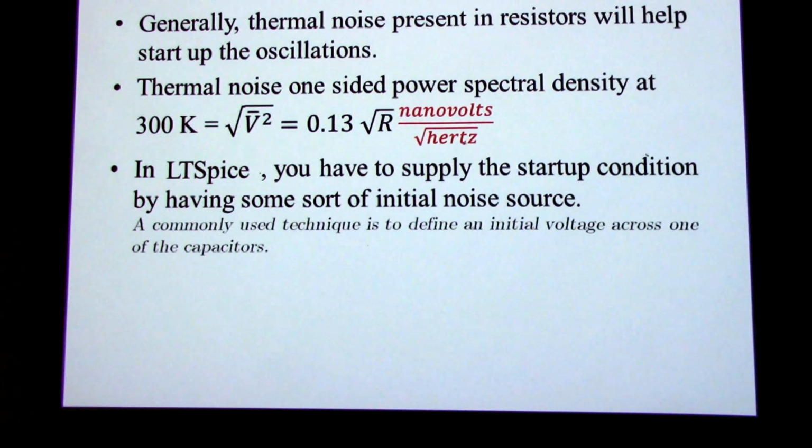That's something like nanovolts per hertz, and there are many things we have to think about, like if you consider the one-sided power spectral density, but we don't have to care because in real life you get the thermal noise without any effort. But in your simulation there is a problem, like there is no thermal noise actually waiting for you there.